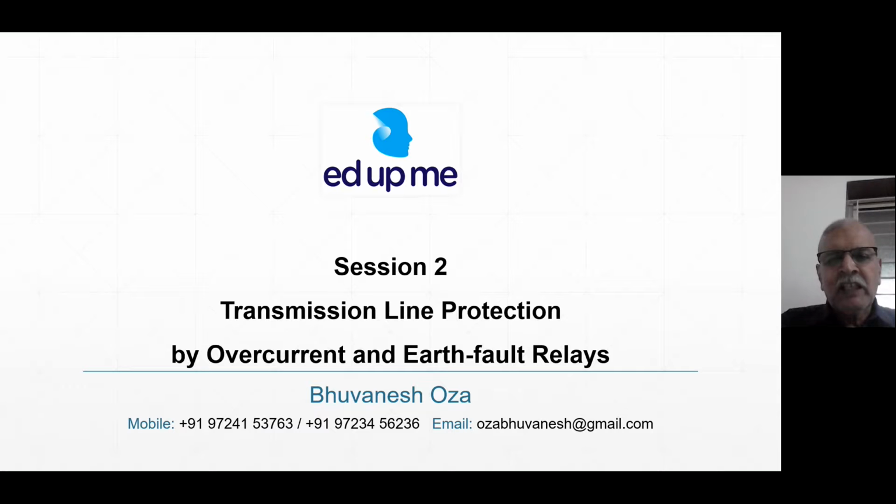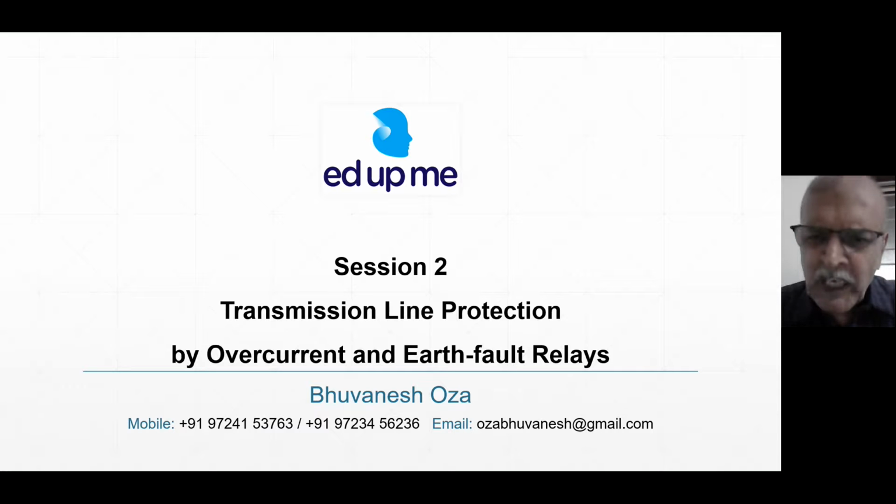And we are taking the first, rather, the poorest kind of protection, because there are many problems in overcurrent and earth fault relays. Distance protection is better, and line differential is the best for transmission line protection. But in any case, we have to learn overcurrent and earth fault relays, as we discussed last time, that 66 kV, 11 kV, and 6.6 kV lines are protected by overcurrent and earth fault relays only, because economically you cannot use distance protection because it is costly.